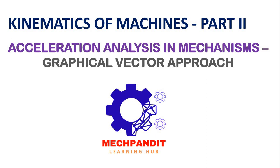Hello everyone, welcome to this session, Acceleration Analysis in Mechanisms using Graphical Vector Approach. In the previous session, we discussed the acceleration analysis of a point on a link, and we observed that the acceleration of a point can be divided into two components. One is the tangential acceleration component and another is the centripetal acceleration component.